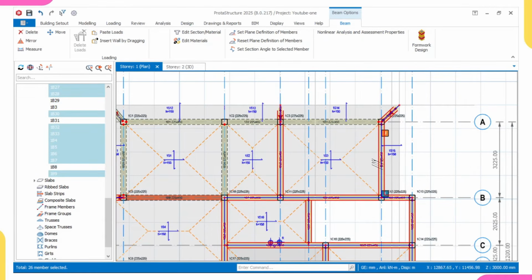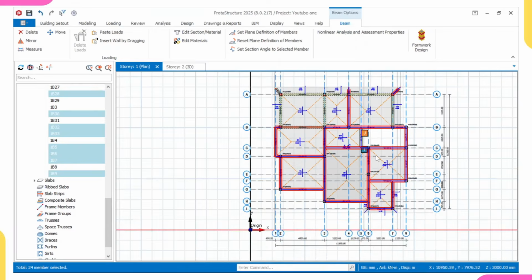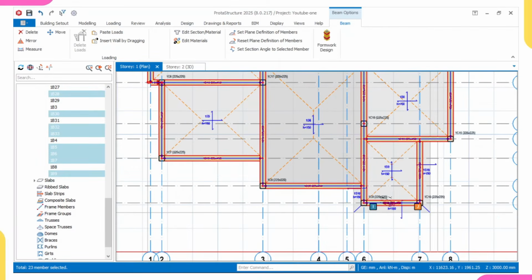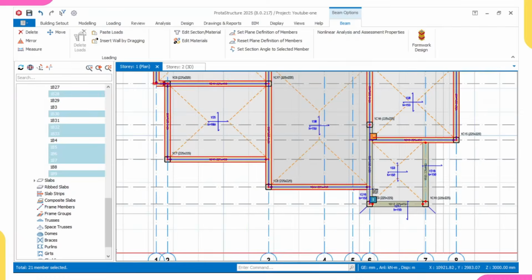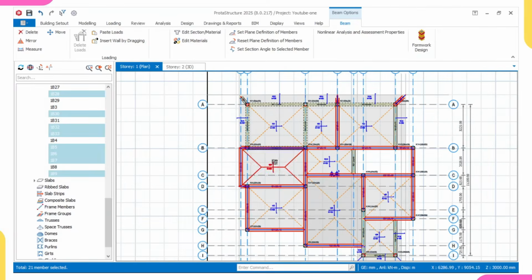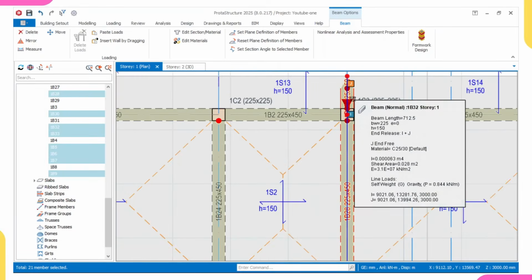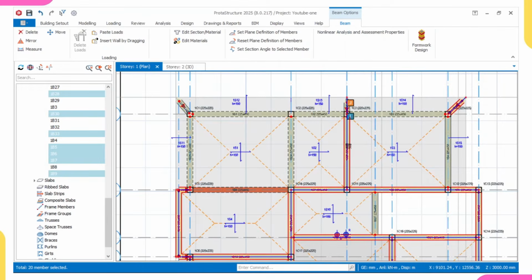I'll also deselect this. Remember, this is staircase. There's no wall load at the entrance of this staircase, so I'll deselect it. And remember, this is my story building. This is my sit out. There's no wall load here. I will deselect it. There's wall load here, but I'll still apply it after. I think we are through. After, I will still apply this wall load. So there's no wall load here. Yes, after I'll apply this wall load because there's wall load there.